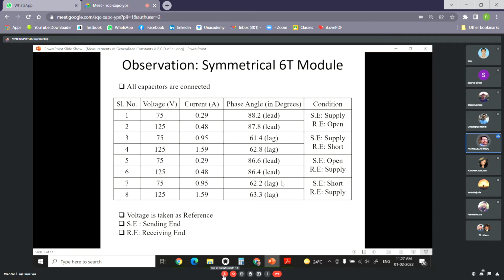So if we have to maintain the voltage at the prescribed values at all times, please remember that it is necessary to maintain the balance of reactive power in the system. That is, the reactive power generation should be exactly equal to the reactive power consumed or absorbed.